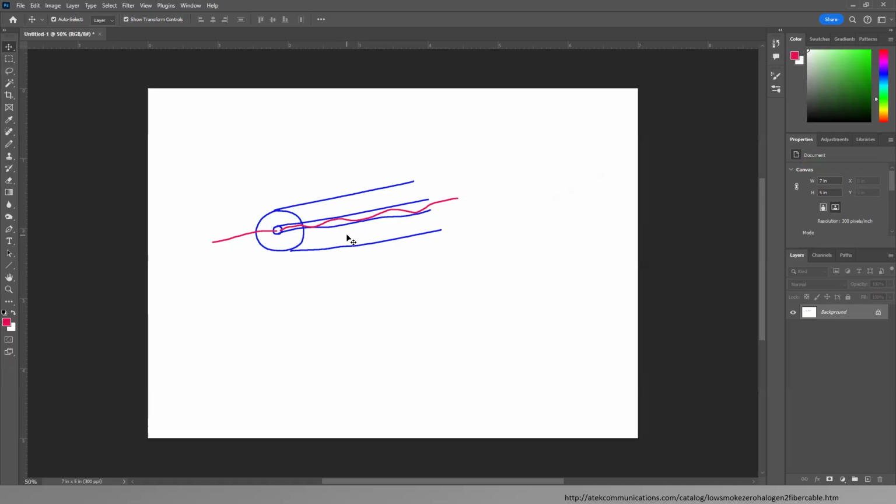Cladding slows down the light less. In that arrangement, this core is also pure glass, but slightly made dirty, slightly doped with some impurities on purpose to slow down the light. And in that case, when you have the interface between one and the other medium, you're creating a mirror effect. So you're creating the total internal reflection. So the signal travels through the core. All right, so that's the quote unquote core of things.